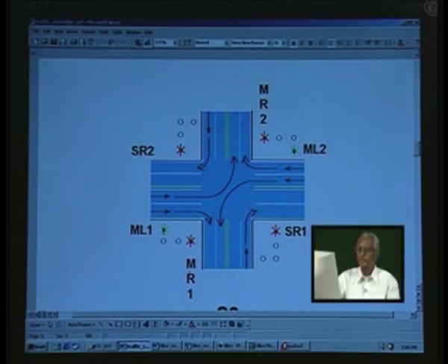So for instance, let us say the main flow traffic has just commenced. If you look here, the 2-digit display will initially be set to 50 seconds, because you have 45 seconds plus 5 seconds of transition, which will go straight here. After this the same counter will be reset to 25 and allow this traffic flow, and this is inclusive of 5 seconds once again for the yellow light, and having done that the total is 75 seconds.